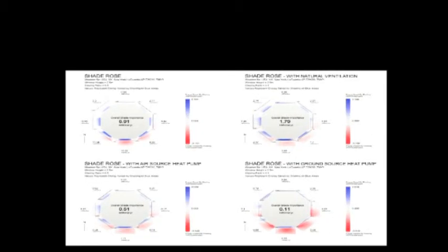And after talking through, one of the things that we found was it's because of the temperature of the municipal water. If you just run through it, it's just enough for cooling. So the energy that you're using is only pump energy. If you were to increase the depth of the shade, you will be penalized in the heating cycle, and then you're using mechanical systems to heat it. So the balance is gone. Which was very interesting because I could have never thought that before. So these kinds of things actually really help us address or think outside the box.